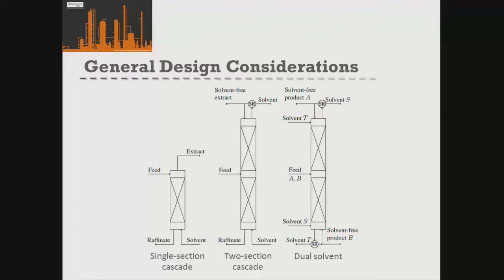As well as having where you just add your solvent and then you recycle some of your extract, you can actually use a dual solvent system. So if you're struggling to get the composition you want, or you have a more complex liquid-liquid system, you can use a dual solvent system where one of your solvents preferentially dissolves the solute and another solvent preferentially dissolves your original carrier. Okay? So that's a much more complicated system, and that's a possibility that you can have.